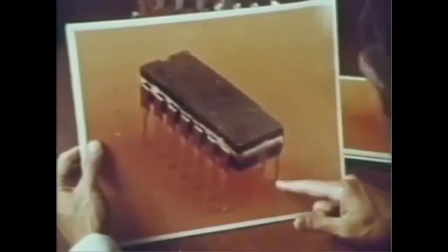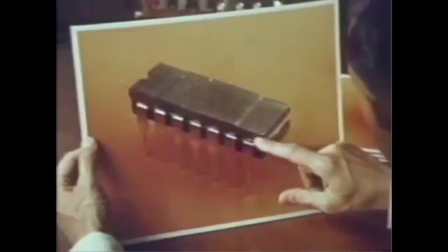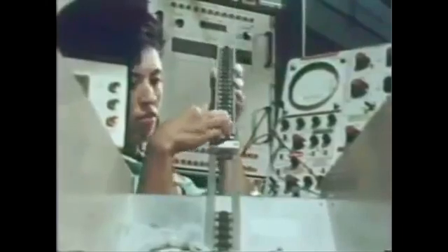The solder glass is peeping out, so that we have to clean that up a little bit by sending the part through the furnace along with many thousands of others, so that the solder glass is all melted in and neatly arranged in place. This is the finished dual inline package. Now that the circuit has been packaged, we must again test it substantially before we would dare ship it to the user. First is a series of electrical tests, many of which use special test equipment, which is again built from integrated circuits.